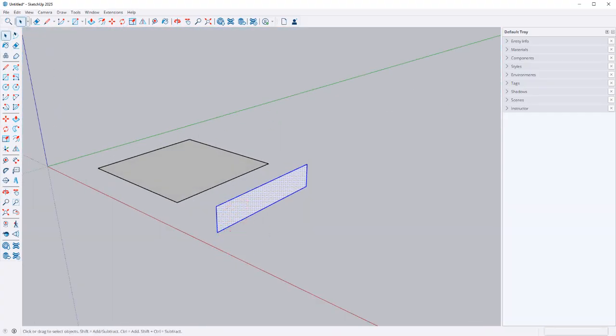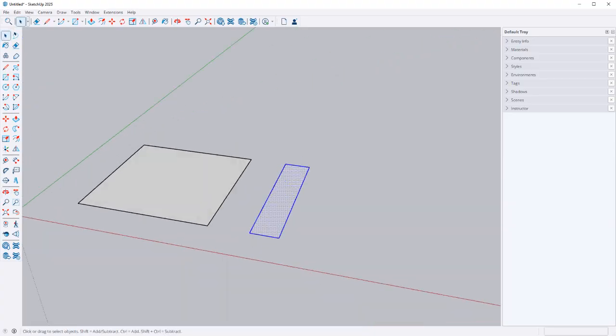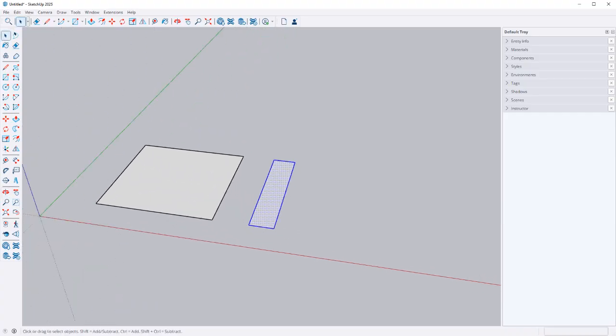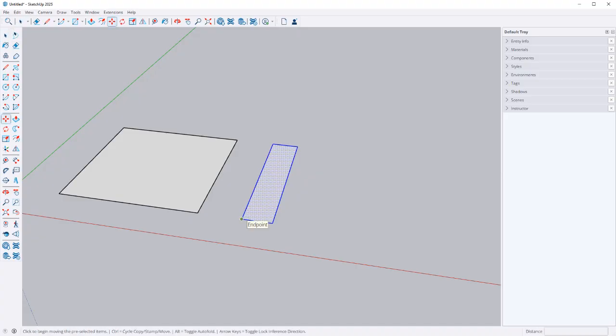Okay. Another cool thing, and I kept accidentally turning it on there out of habit, is the copy move tool. I briefly, I think, showed you guys how to do that in AutoCAD, but it doesn't get a lot of use there, whereas in here it does. So if I move something off in a direction here, I can hit the control key to toggle a move copy.